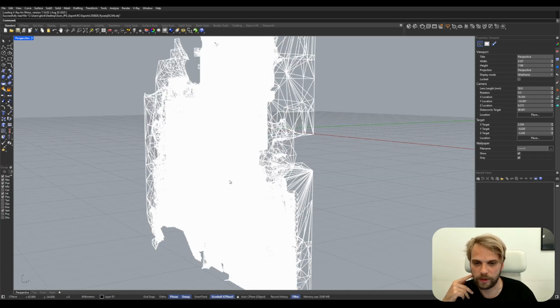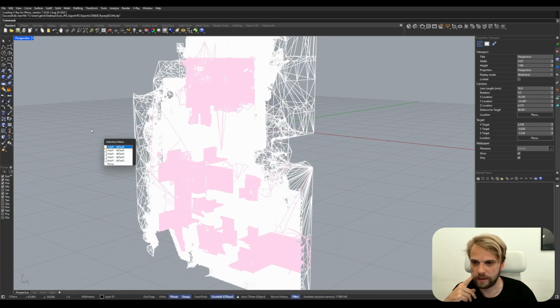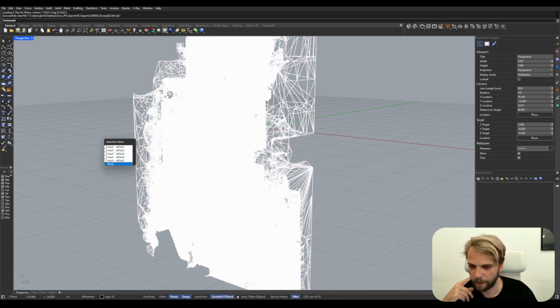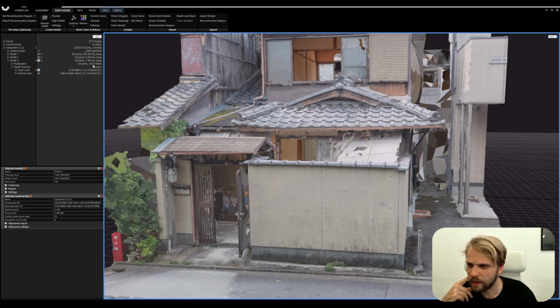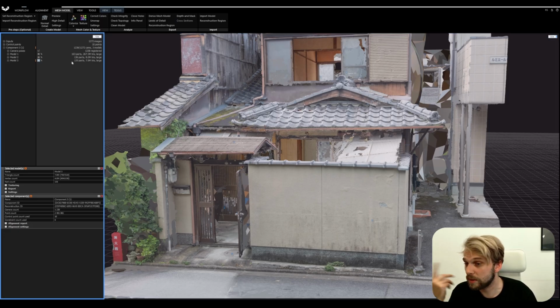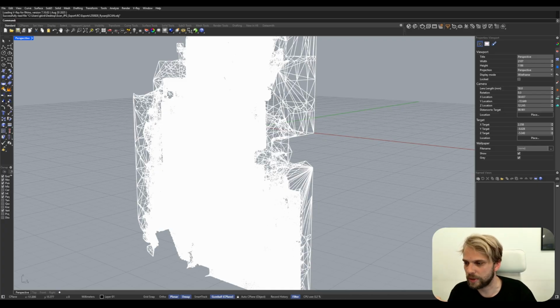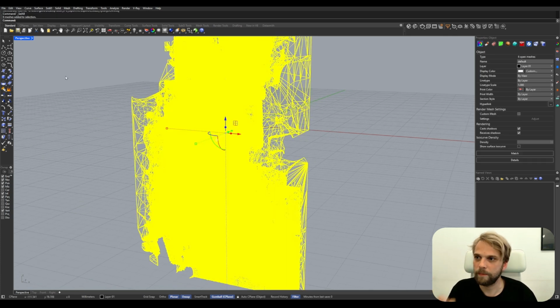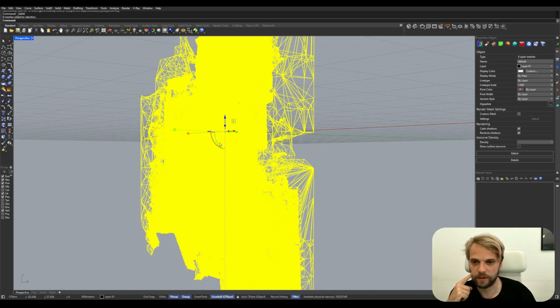So once this is imported, let me just select the whole thing, and it's not going to be lightweight. It says 135 parts in total. I don't think it's going to be 135. Rather, it's going to separate the mesh according to the textures, right? So if I press Control A, 6 meshes are selected. So it's actually only 6 parts. You can't really join the meshes, but you can group them together. If you join them, the textures will all mess up.